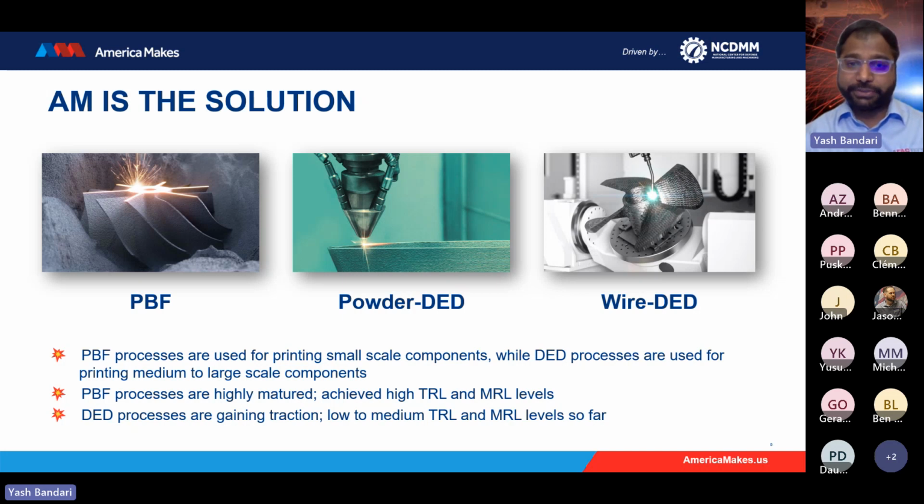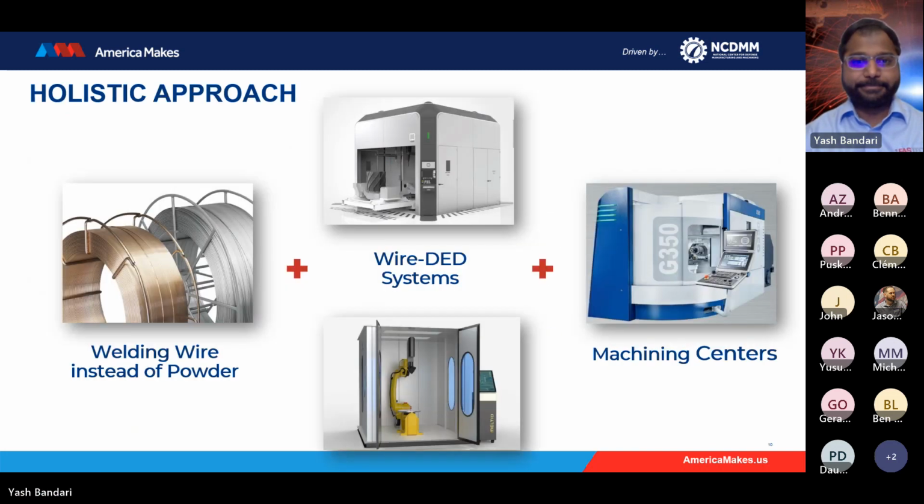The wire is a lot more safer compared to powder. And the point is the properties as well. So you don't need to do a lot of post processing with wire as opposed to using with powder bed fusion or even with powder DED. So this is a holistic approach that we took 5 years ago, and so that's why we apply wire DED and then combine it with machining and then inspection.